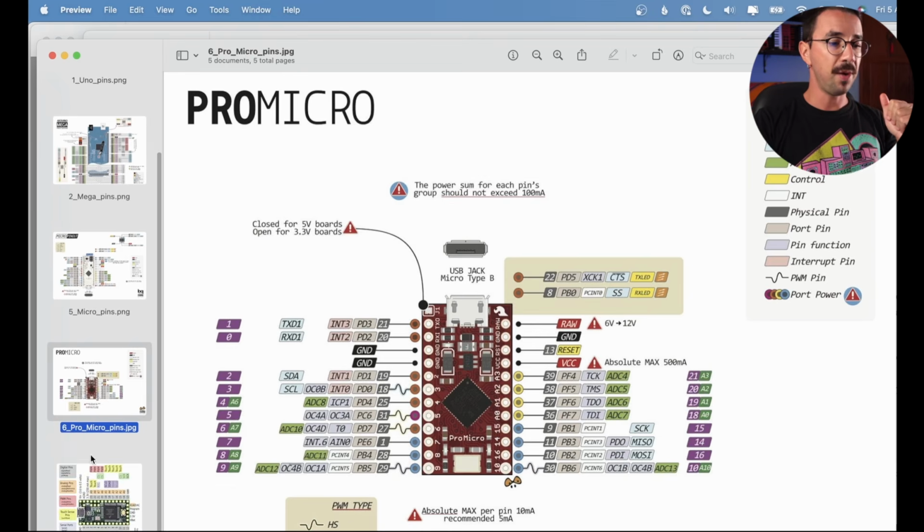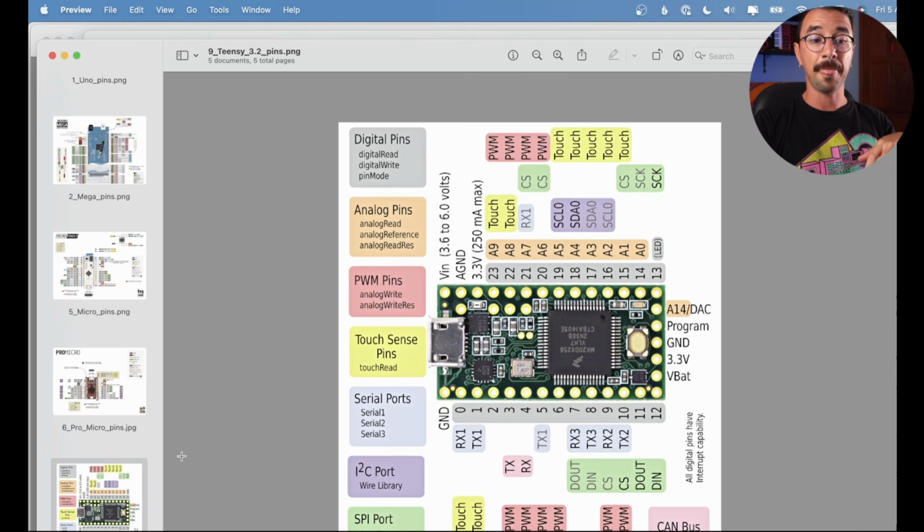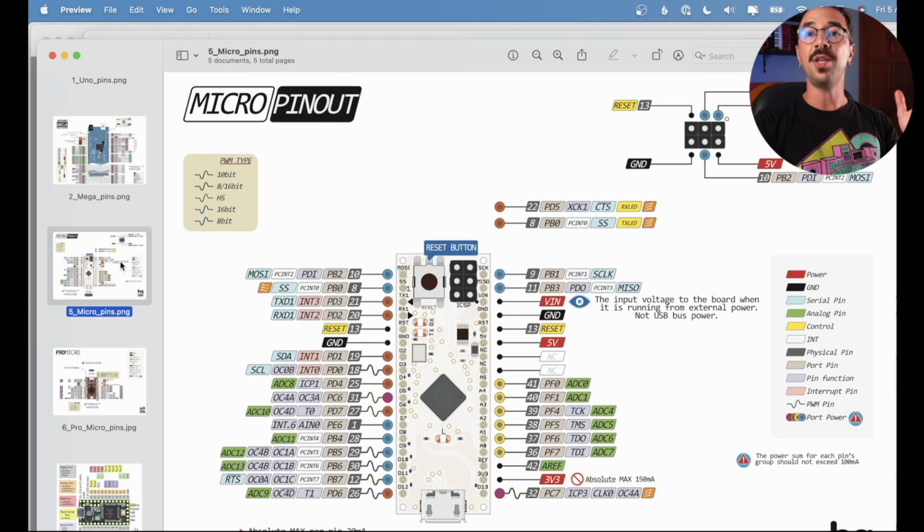If you want more, for example, you can use a Teensy board that has more pins with interrupts. Bigger Teensies have way more pins. But also if you want to use more encoders with a regular Arduino, you can use a port expander such as the MCP chips, which I teach how to use inside the Making Music with Arduino course. Each IC has 16 pins with interrupts, so you can use up to 8 encoders in each IC, and you can use, I guess, up to 8 ICs in an Arduino. So 64 encoders, that's a lot.